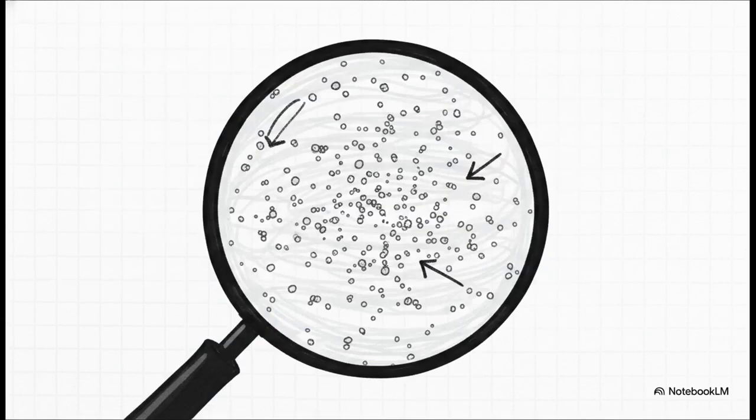But let's get into the weeds. What exactly is it chemically? Well, as all that carbon rushes out, it has to go somewhere, right? It precipitates and settles. So what you're left with is a ferrite matrix. Think of that as your soft base material. But dispersed all throughout that base is what we call fine granular cementite, or Fe3C. Basically, the carbon recombined with the iron to form these incredibly tiny, fine granules of cementite, and they're just embedded right into that softer ferrite background.